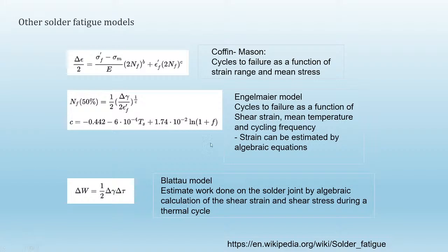Obviously, these models are all established for particular types of packages. These methods are typically really good if you're looking at more simple packages. So I think someone mentioned QFN. That may be a basic package you may be interested in, or resistors, capacitors, leadless devices, surface-mounted systems. You can probably estimate the strain. Not probably, I know you can estimate the strain pretty easily, and you can fit these into the coefficients and get the results.